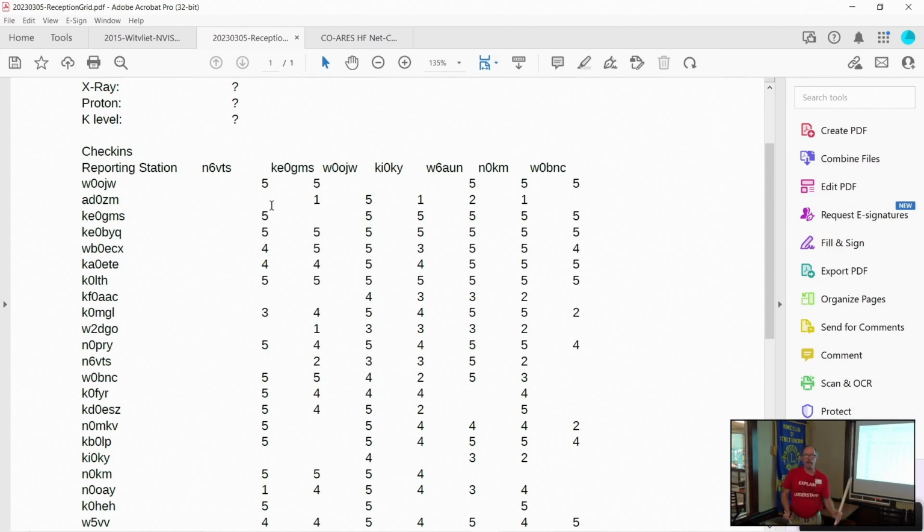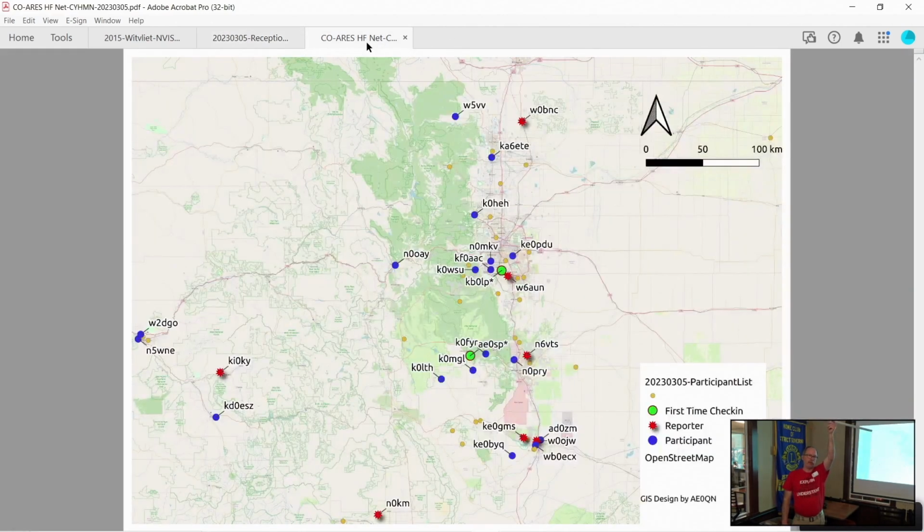Well, a really great NVIS antenna is a dipole cut for the band, a quarter wave above the ground. On 80 meters, that's about 66 feet above the ground, which is kind of tough. It's doable, but it's kind of hard if you go out to set up somewhere on your own to get a horizontal 80 meter dipole 66 feet off the ground. It's easier if there are big tall trees in the right place and you can throw some rope over some tree limbs and hoist something up.